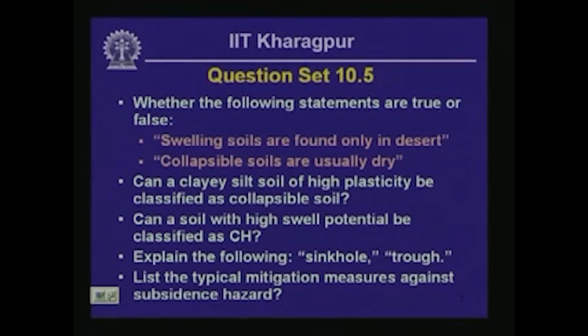If you recall from what we discussed in the previous lesson, sinkhole is a situation where a soluble channel forms at some depth near the surface within a volume of soluble rock such as poorly compacted limestone. In such situations, if a cavern forms very near to the ground surface, the overburden above the cavern is unstable, it cannot sustain its own weight or the structure that is supported on such covering above the cavern, and as a result the overburden usually collapses into the cavern. As a result, sinkholes develop.